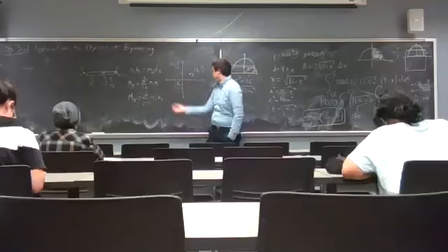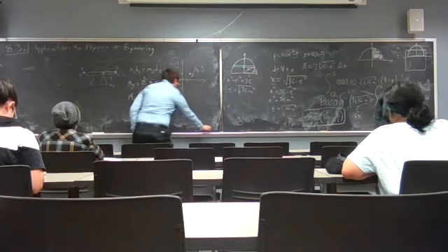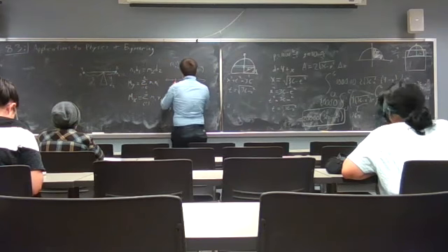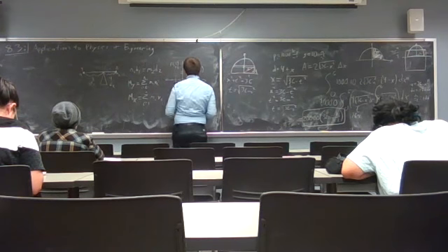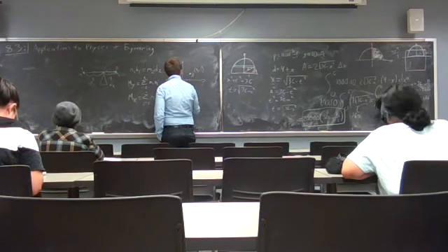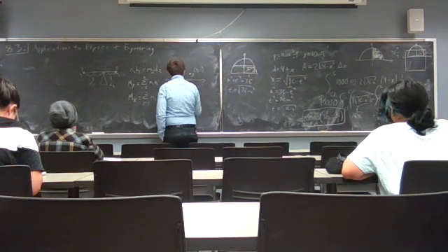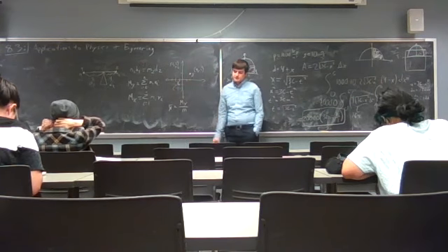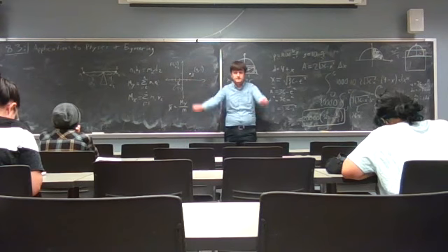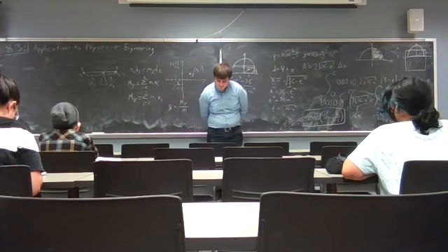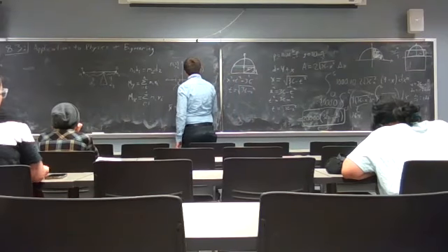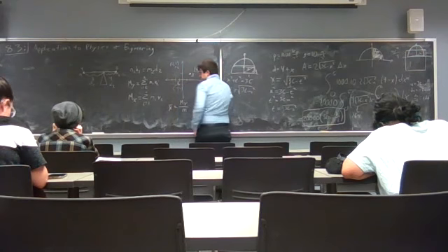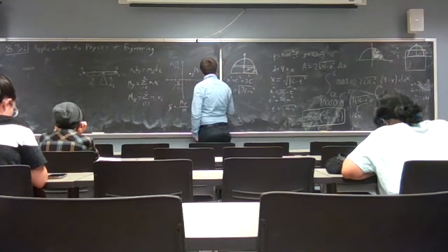And the way that we do that is I take my moments, right? So for the x point, because we want to find a point ultimately, to get the x point in this situation, I'm going to take the moment in the y direction, and I'm going to divide that by the total mass, the sum of m. To find y bar, which is the center, I'm going to take the moment in the x direction, and I'm going to divide that by the total mass.